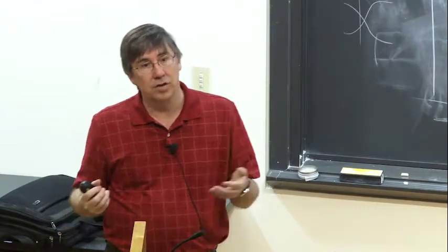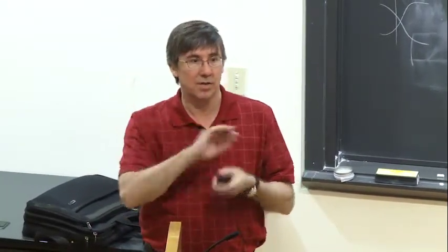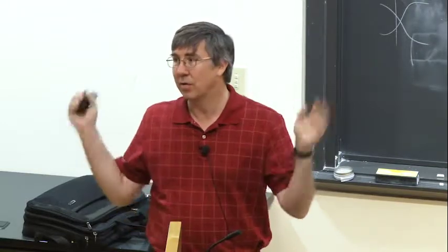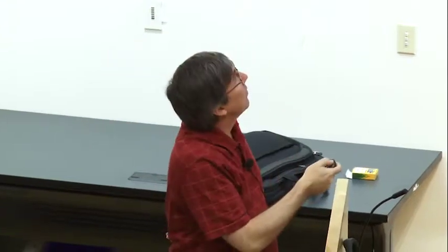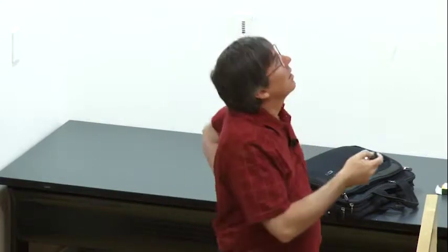Or if the code's good, it'll tell you, I can't integrate this. The time step will keep dropping. At some point, it'll say, sorry, hitting the numerical round-off error in the calculations. Too bad. But a guy named William Gear, who I think was working right down the road from here in Princeton, figured out the first algorithm that could solve the stiff ordinary differential equations. So if you could write down the chemical kinetic equations, at least for a homogeneous batch reactor, you could solve them. So that was a big advance.